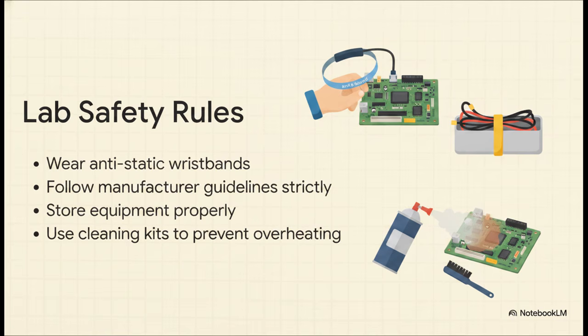For instance, when you open a computer case, you must wear an anti-static wristband. Why? Well, because the static electricity naturally stored in your own body can literally fry a delicate motherboard in an instant. You also need to strictly follow the manufacturer guidelines, store everything properly so cables don't fray, and use those cleaning kits. Honestly, dust is a computer's worst enemy. It acts like a thick blanket, causing parts to overheat and completely fail. Keeping it clean keeps it alive.